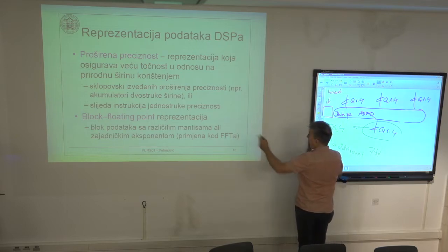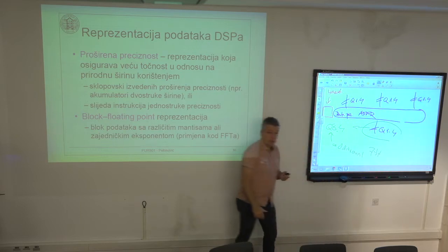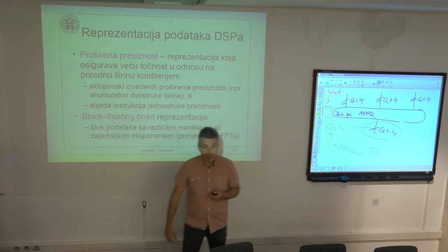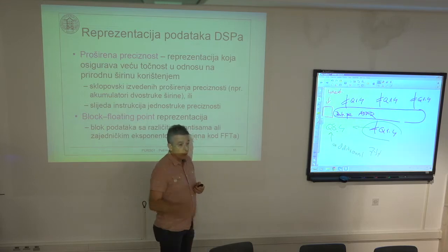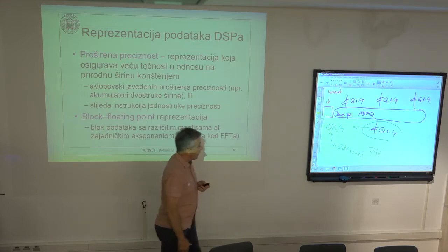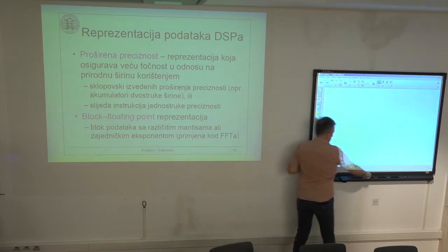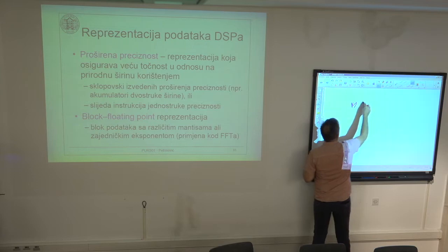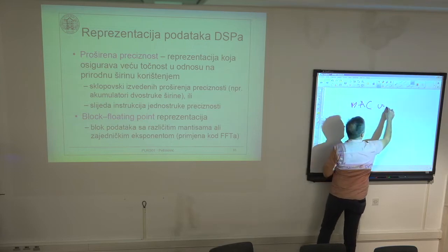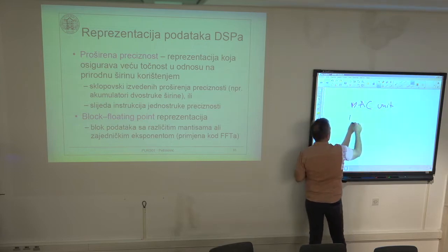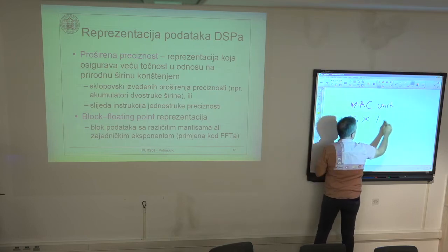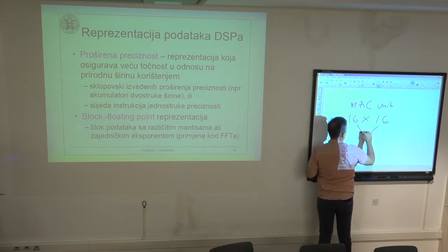Okay? In the actual implementation that we will illustrate for the DSPs that we will be considering in the course, this kind of architecture is used in the MAC unit, because this MAC unit multiplies two 16-bit values into a 30-bit product.